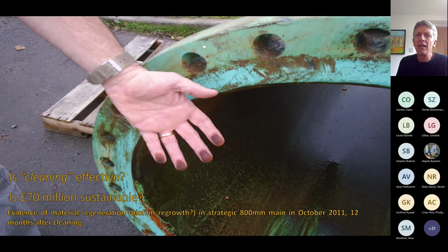The problem is if you clean it, and whilst a lot of those deposits are historic, this stuff comes back remarkably quickly. So this is an example of an extensive cleaning programme in one of the UK cities. The water company got permission and ran a £70 million cleaning programme. They really aggressively went into all these pipes, replacing non-preferred material, lining it, cleaning everything, putting foam swabs through, all sorts of things. They thought they had this beautiful, shiny, pristine system. Just 12 months later, though, they were starting to get discoloration contacts again.